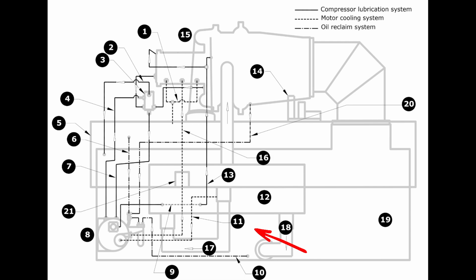On that Dunham Bush, as an example, when we calibrate that valve, you're watching your sight glass and you want to see it flashing. When you get a stable evaporator and everything's smoothed out and you go to calibrate that oil return valve, if you see a full column of liquid in there, then you're too far open, and you'll end up sending too much liquid through. You want to tune it to where it's got a really heavy mixture, flashing very heavily as it returns back.